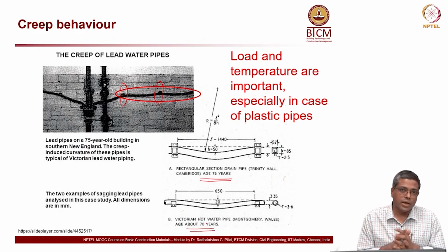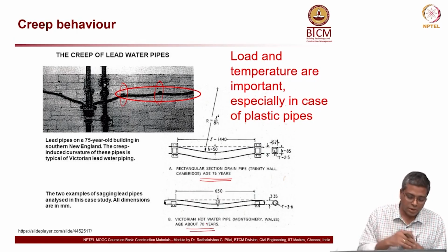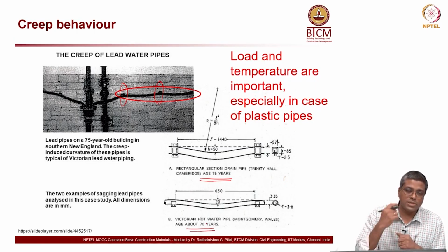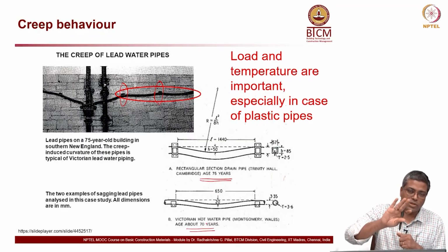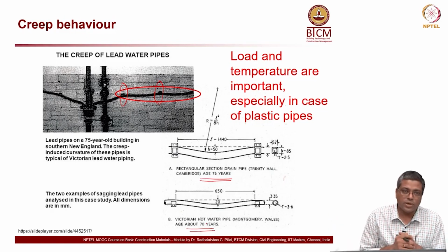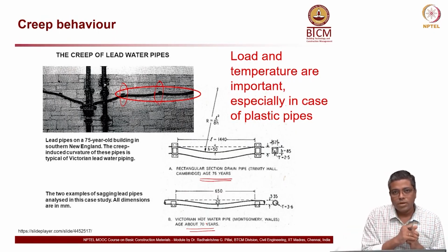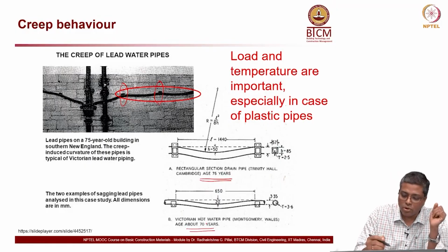One example where you can see this creep behavior very easily is when you go on the road and look at the barriers between the lanes on our highways and roads. I am talking about those black and white painted barriers. You will see electrical conduits fixed onto the side of them. Have you seen anywhere where it is a straight line? It's very difficult, right? Because you will see that from clamp to clamp it has a sag. Okay, so clamp to clamp, I am going to draw it here.